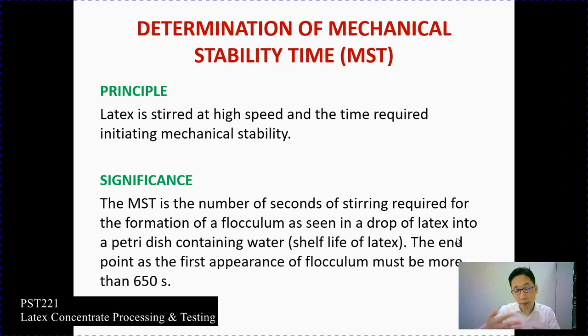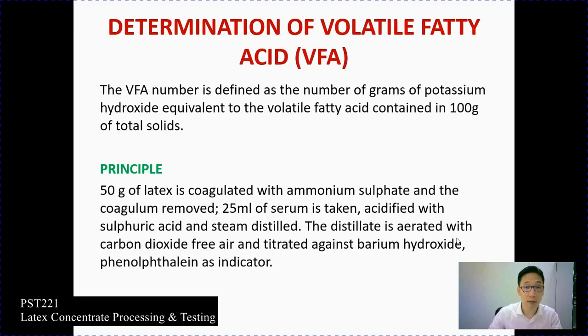If you do the dipping product, it will pick up non-homogenized amounts of rubber during the dipping process, so it might cause defects in your final products.